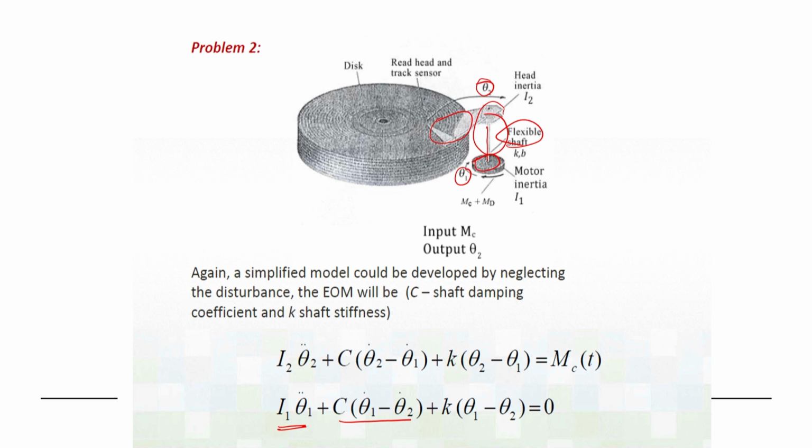So, in this equation we can say that the first is the inertia force, the second term is the damping, and the third term is what you call the spring force, the resistive force from the spring. And for equilibrium, all these three things together should be 0, or else in the other case, for example, there is a moment that is applied on the system. So, this is the way we can represent such a system.